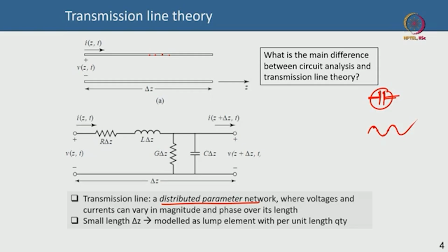So, a transmission line is basically, as I said, two lines, a signal and a ground. Qualitatively you can think of it like that, and we say that this is an incremental length delta Z. What we are going to do is derive the expression for, or understand, something called the characteristic impedance Z0 for this transmission line.